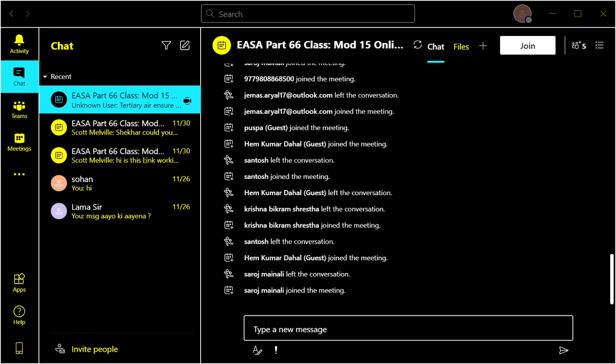Oil tank though. So in the tank itself, what we're going to have? Well, we're going to have oil, definitely. How much oil do we have? Well, we need some method of ensuring how much oil is in there. Now you have various different methods. On this one, we'll start over here. We've got a sight glass, just a little window, with calibrated lines down the window, so it's a visual. You can tell straight away how much oil is in that tank just by a little air bubble at the top, because you always have air. If you can't see an air bubble, you're either too full or it's completely empty.